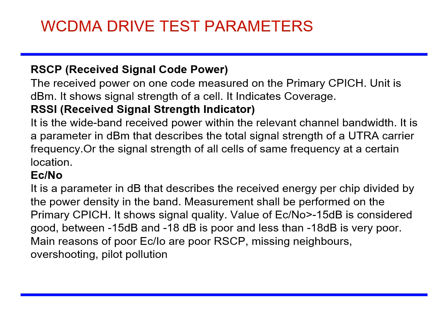Main reasons of poor Ec/No are poor RSCP, missing neighbors, overshooting, and pilot pollution.